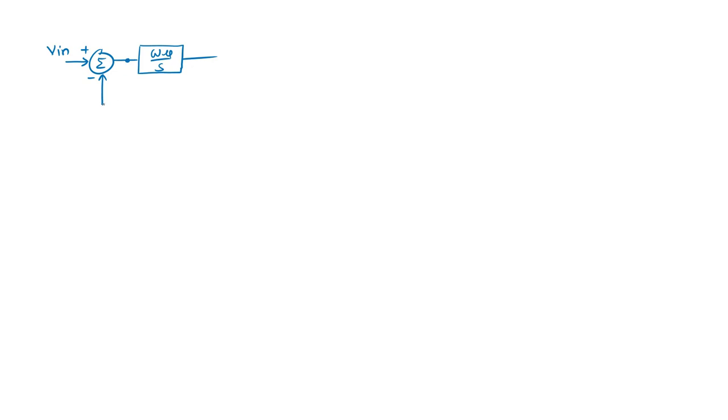Okay, so what it does is, if this is a beta, it actually takes the difference here. If it is used in negative feedback, then we can say it is taking the error voltage and integrating it. So this is the op amp structure, the internal structure of the op amp. First I relate this thing with our op amp, then we'll proceed at the GM cell level. Then this will give the frequency response.